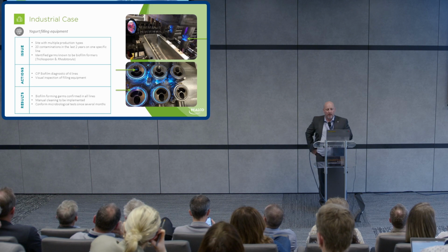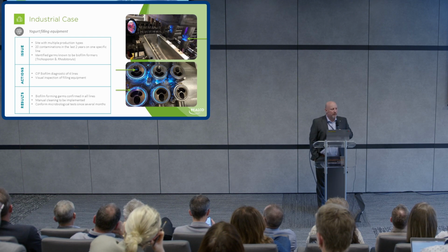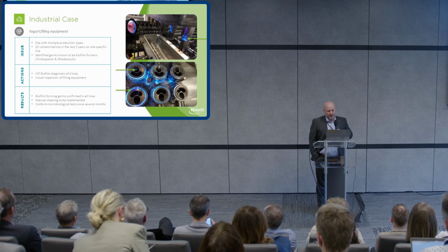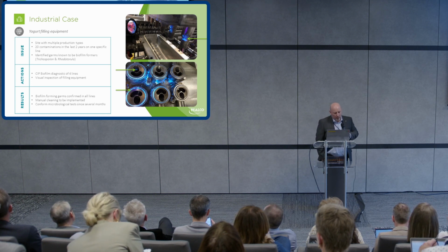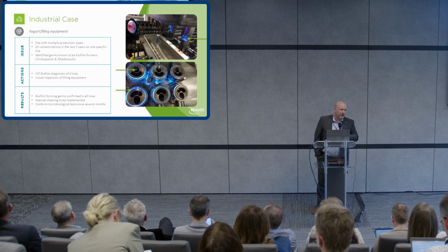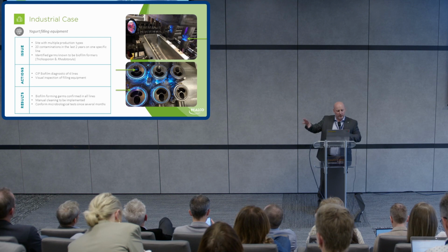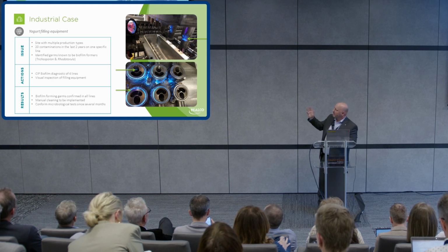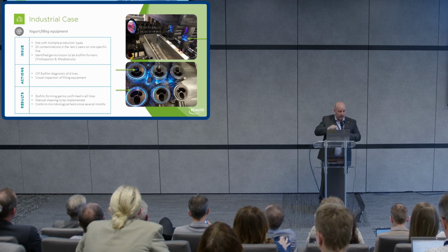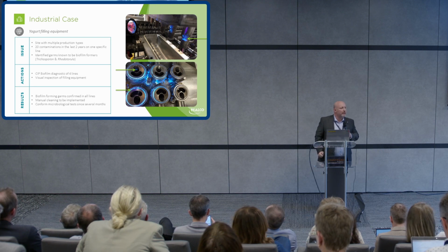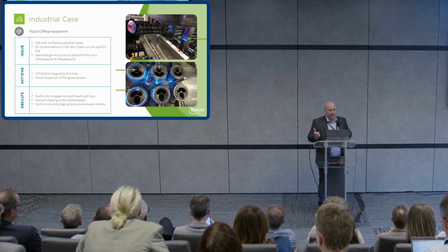This first one is a company that called us because they were facing some sporadic contamination, 20 contaminations during 2 years. They asked us to investigate where this contamination could be located. We went on site and did an audit on closed circuits, different lines, tanks, but also investigated the dosing system. We asked them to dismantle some parts of the equipment, and you can see directly that some parts were not clean, after the cleaning and sanitation, before restarting production. Thanks to the UV light, some parts were not fully clean, so we asked them to do a swab there, and there was some contamination.